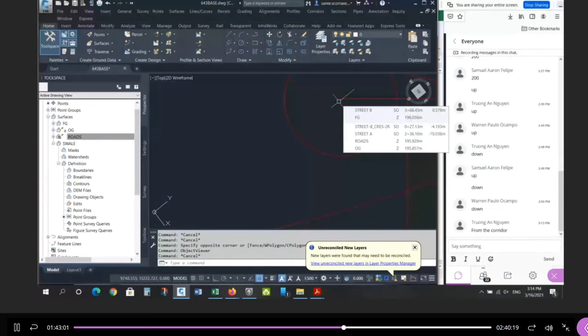That's the corridor elevation. So in this case, the top elevation, approximately, there's a more accurate way of doing this, but approximately is 195.929. I would just work with two decimal places, 195.93. Subtract 2.75, subtract the pipe size. This is the dead end. I'm going to use a 0.15 or 150 millimeter pipe. Now I have my invert at the top end, and I'm going to go down the pipe, subtract the drop, down the pipe, subtract the drop, and so on.